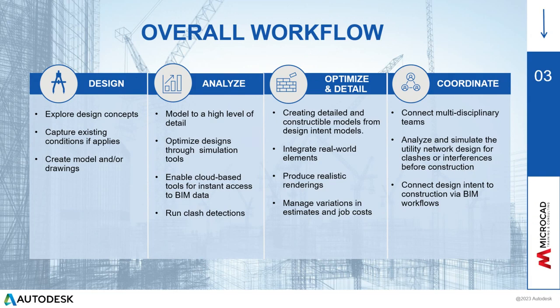The third stage in this workflow is optimize and detail. So it is time to be more realistic. More than knowing locations and sizes, accessories and real-world elements can be added. For example, in a plumbing plan in the schematic design, we normally show locations and sizes. But in this stage, we add the real length of the pipe, where it should be, the materials, the hangers, and so on. By having everything detailed and in perfect conditions of modeling, realistic renderings and cost estimates can be performed.